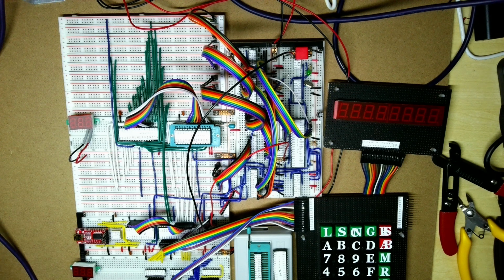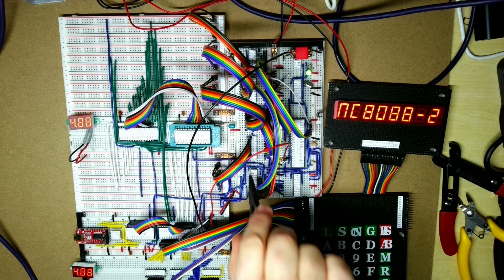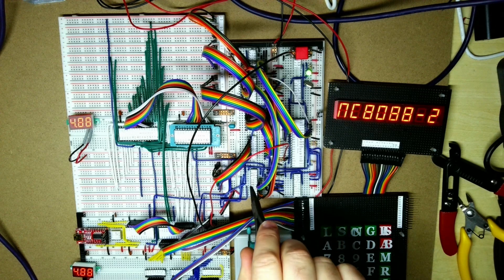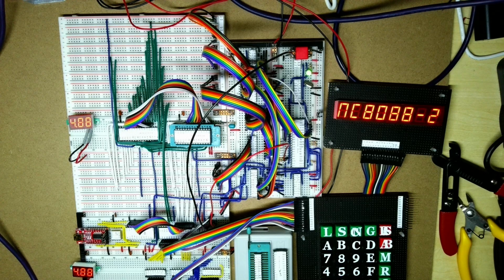Okay, so we're just going to make sure this is still working before we start making the changes. That's Nanocomp 8088 version 2. And if we just go memory 0, 01, 02, 03, go back to memory 00, that's 0, 1, 2, 3. So we're able to store data and reset is working. So what we're going to need to do here is swap out this PLD for the one I've just programmed here. This is the V3 version, which is using the IO read and IO write rather than the memory read, memory write.